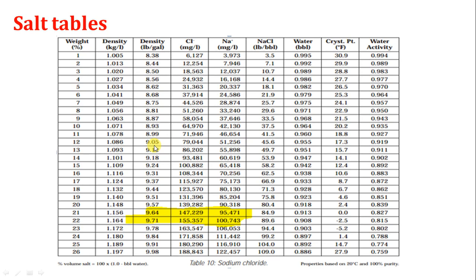It depends also on many things that I take into account while making a program or a mud proposal. So take care, this is very important. I use salt in order to keep the solids very low, and also not to use too much solids or too much barite.